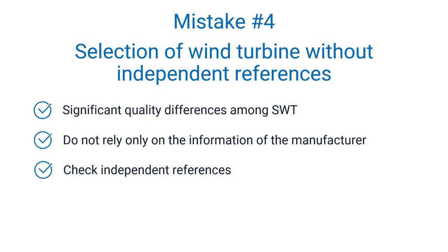This might be a certification based on IEC 61400-2. Also, a successful and proven operation on an independent test site is helpful, for instance, stated with an independent report on the power curve. A long track record of a manufacturer with good reputation is also helpful. And well, get statements of owners of a small wind turbine. Talk with people that have a specific model installed for some time.